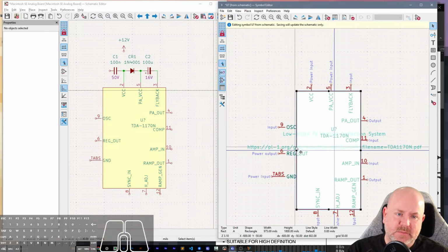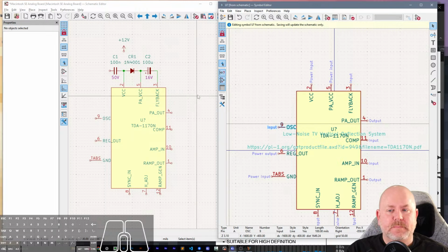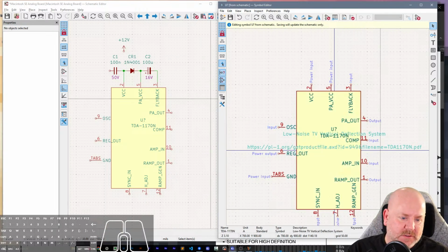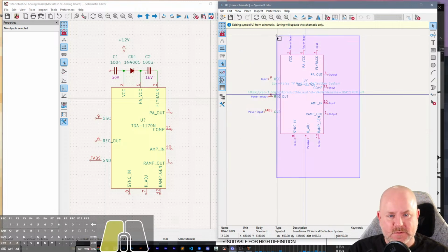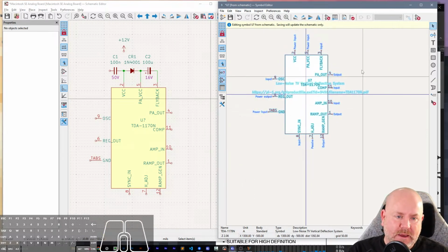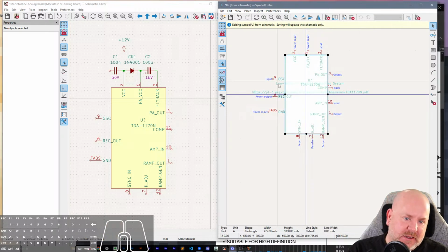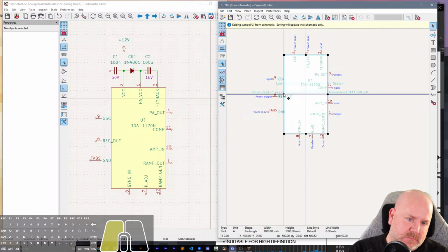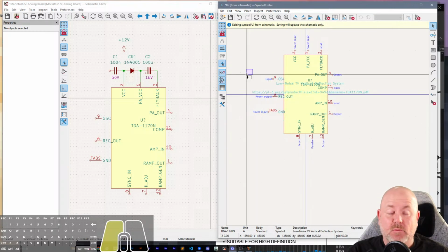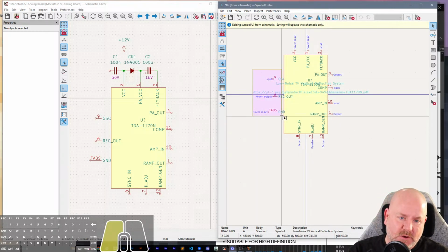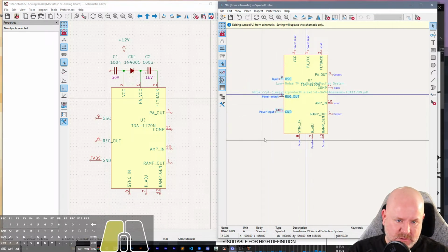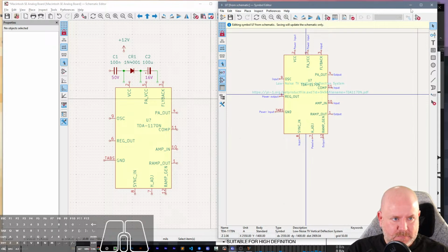Looks like 1, 2, 3, maybe that many. Yeah. Maybe one. Okay, so now what I'm just going to look for is what it's going to take to center the part, which means we got to move our schematic, the other components, but that's okay. It's not the end of the world. There we go. So now I can move. I'm going to drag to the right to only get the pins. I don't want any of these text fields. All right, so we'll save that.